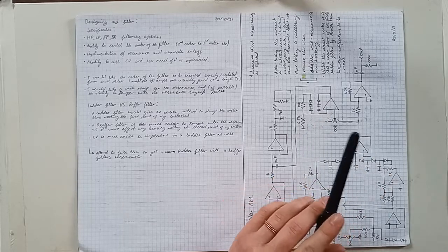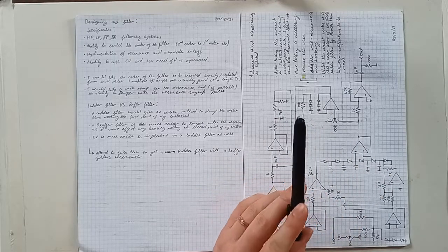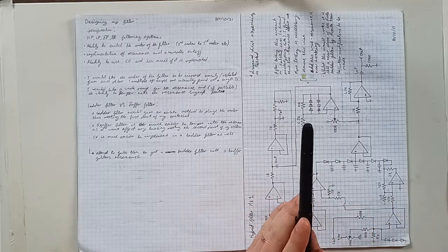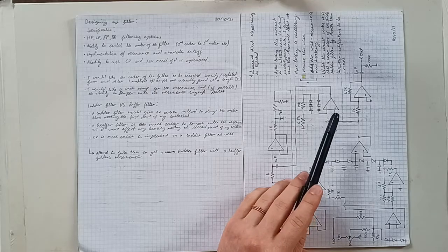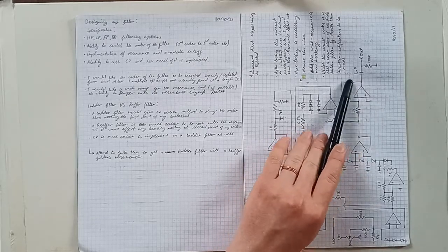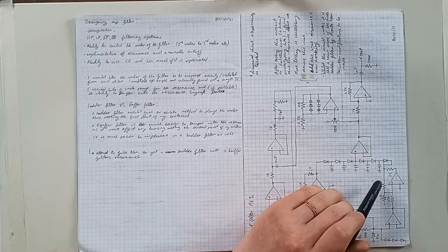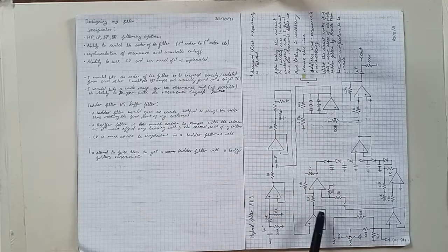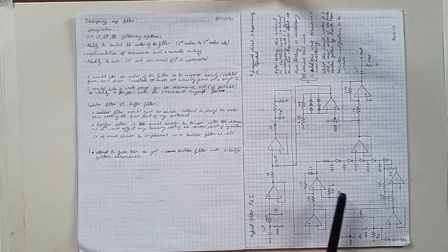You can end up with different responses for different amplitudes of your signal. So you want to try and keep it as tight together as possible. And I realized if you then just take the resonance from after the amplifier in that circuit rather than just before, you then end up with nice working resonance with your ladder filter.